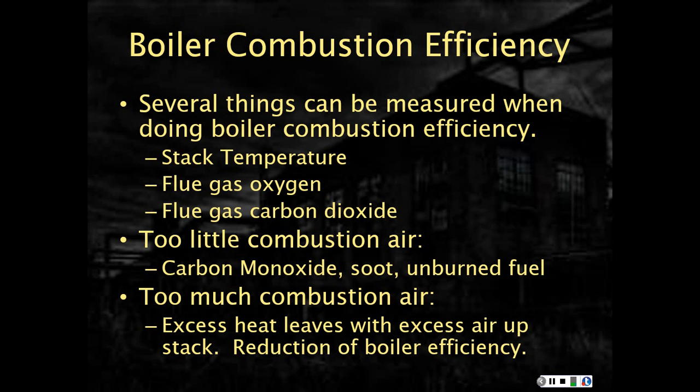Several things can be measured when doing boiler combustion efficiency. The most common items are stack temperature, or exhaust gas temp, the flue oxygen percentage, and the flue gas carbon dioxide percentage. Those are the most common things that are measured.